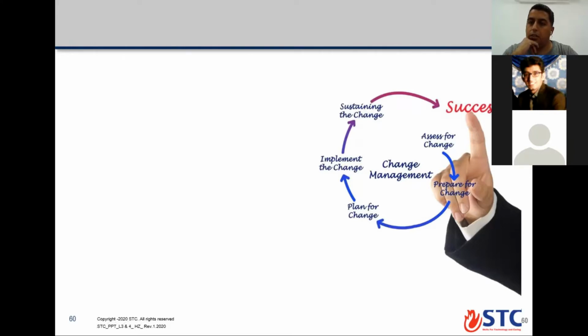This is our management of change. If you have a vital change in the plan or program, a big change, you need to get the paper approved and sent from the office to the site. That means all personnel are on the same page and agree to do this change without taking any verbal instruction. This is the MOC system, or management of change.